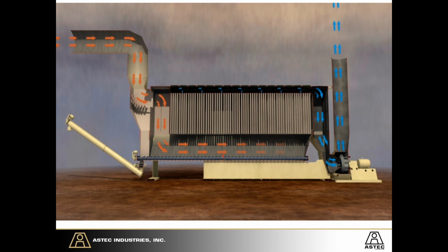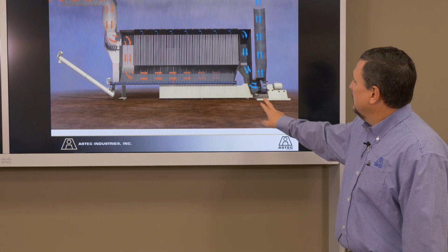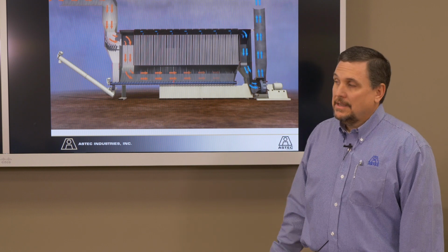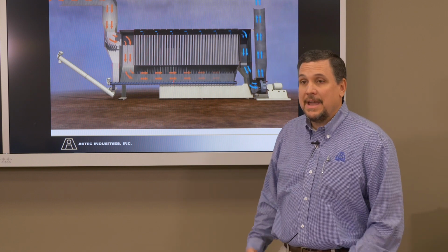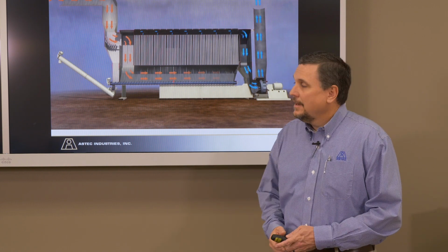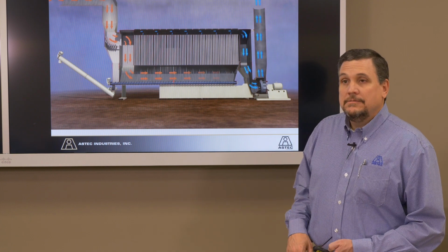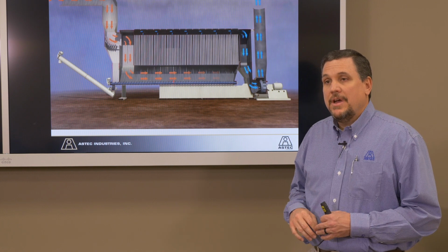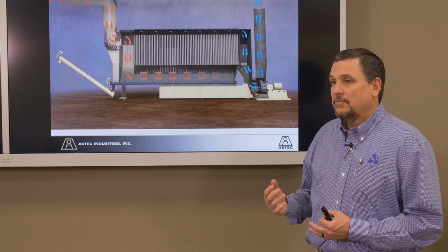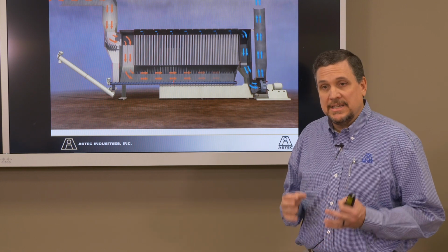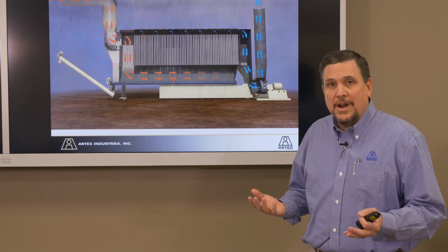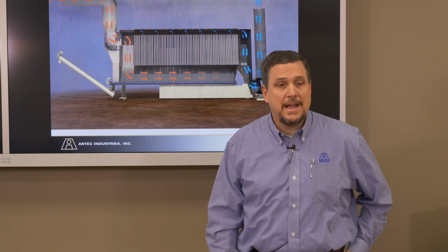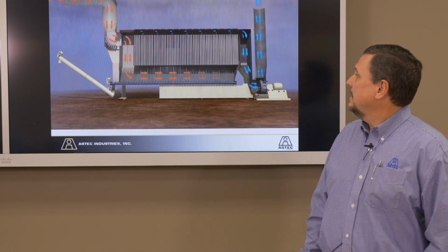And that's what you call your baghouse differential. One thing in the United States, every state has to go to a particulate test. And that particulate test is basically how many particles are you blowing into the air. Everyone has to meet that requirement. The other thing that you see in some states is you have to do flue gas analysis, and that really is how you tune that burner to be as efficient as it possibly can, and you have regulations you've got to meet on that. But everyone has to make sure they have their baghouse maintained well for the particulate test.